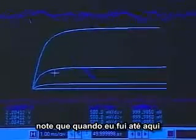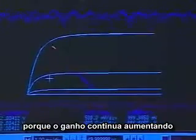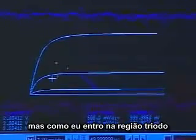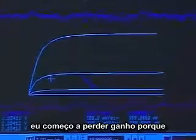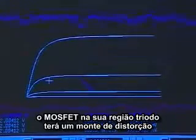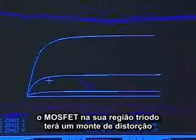So notice that as I went up here, the volume kept increasing because the gain kept increasing. But as I got into the triode region, I began to lose my gain because, remember, the amplifier doesn't have gain in the triode region. The MOSFET's in its triode region, and we also get a bunch of distortion out there.